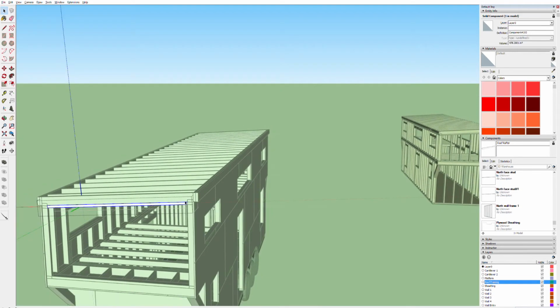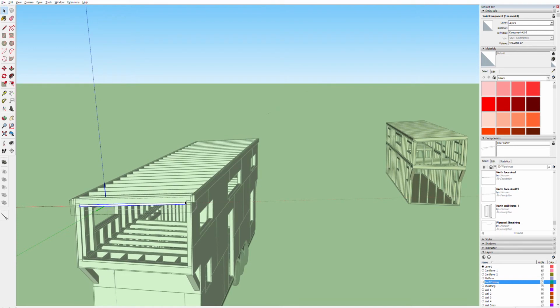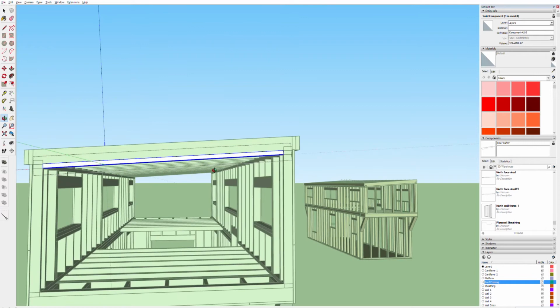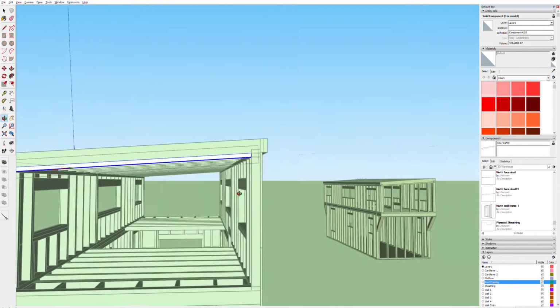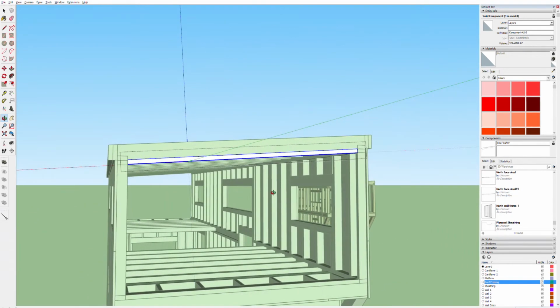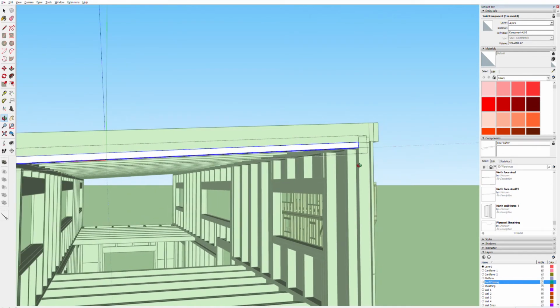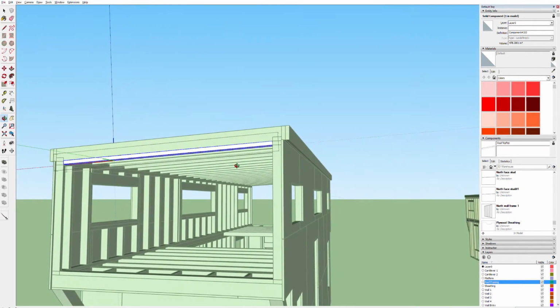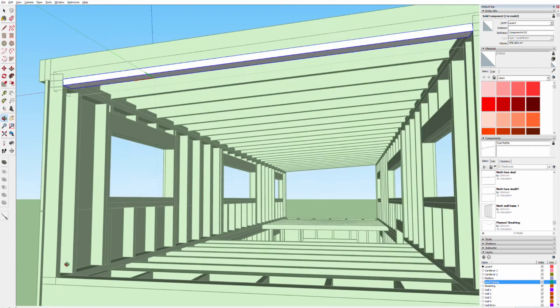Okay. So, I guess it's going to take a little bit of load, but really this is not very load bearing at all. All the load is really going to be off the points where these rafters are hitting. Any kind of bow on the ends of these rafters would take a little load on this little wall I'm making, but this really isn't a load bearing wall. This wall could disappear and everything would be fine. The roof would hold and everything would be great. So I don't think I'm going to double plate that, is what I'm saying. I don't think that's necessary here. So let's just get right into it